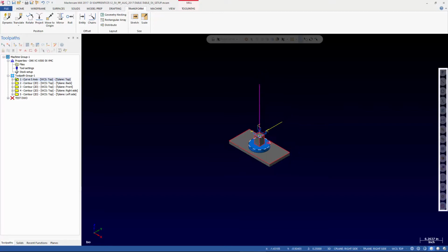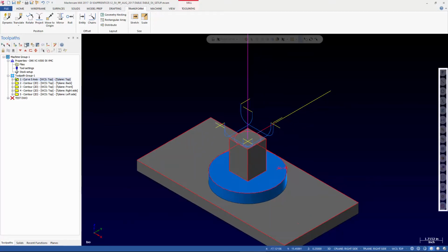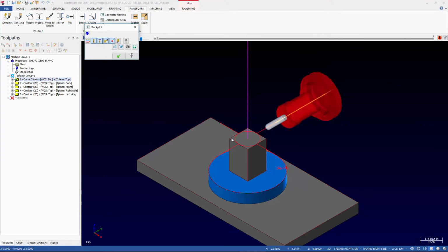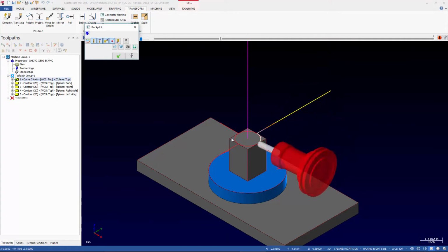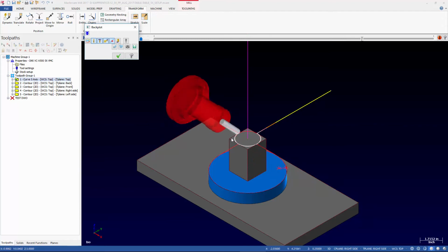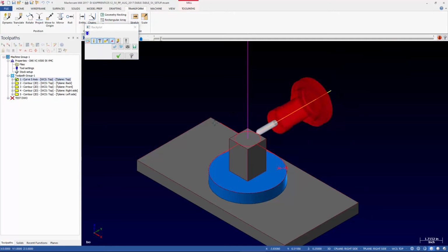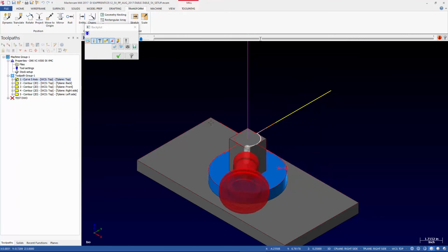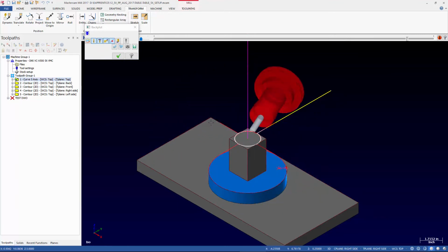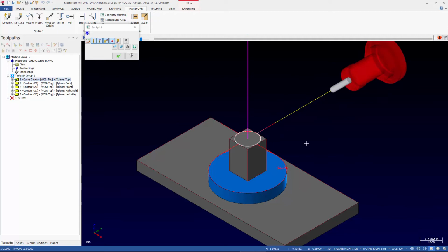So first thing we'll do, you can see I've got, for my curve 5-axis toolpath, I'm cutting the classic circle. I just want to spin my primary axis. I want to drop down in Z, so I want to rotate A. I want to drop down, and I want to spin C to make a cut. Almost always without fail, it's the first test I do, because if you can't make that work, how the hell are you going to make an impeller? I mean, it's a serious question.